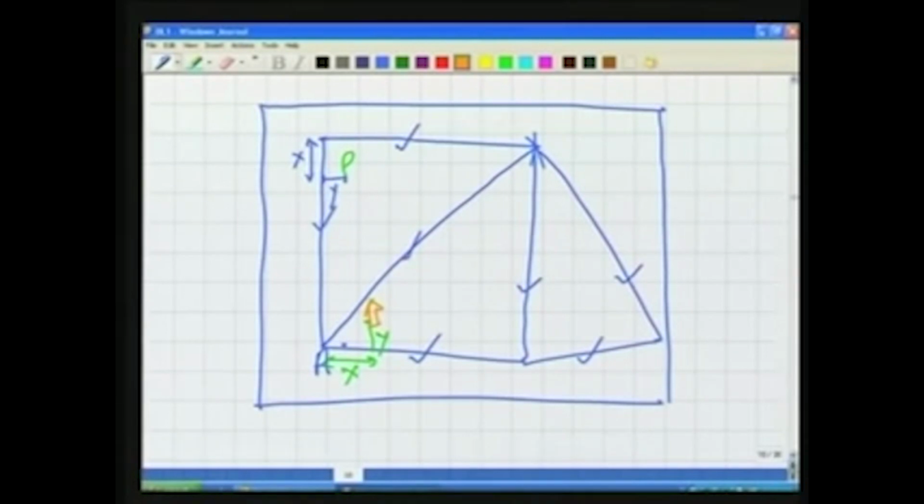Okay? So, this is what we did, we are working first in the whole, the skeleton of the area we are bringing here. We are not bothered at that stage about the features. But in the second stage, now working from whole to part, we make use of the control network, these triangulation figures, and then we start plotting each and every detail. Now, what is the advantage of this? Why should we do it?